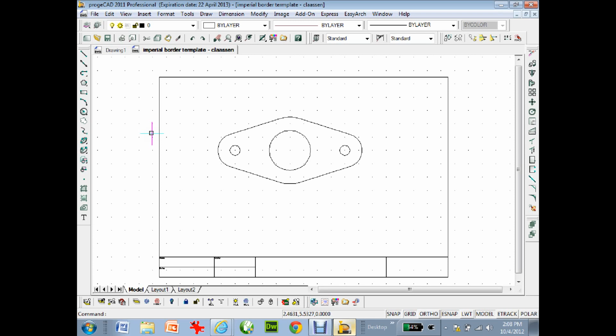You can't use fillet on this one. You have to use trim to cut the parts out. No, because you won't have the line tangent. Trust me. Okay? No, it won't work. Okay?